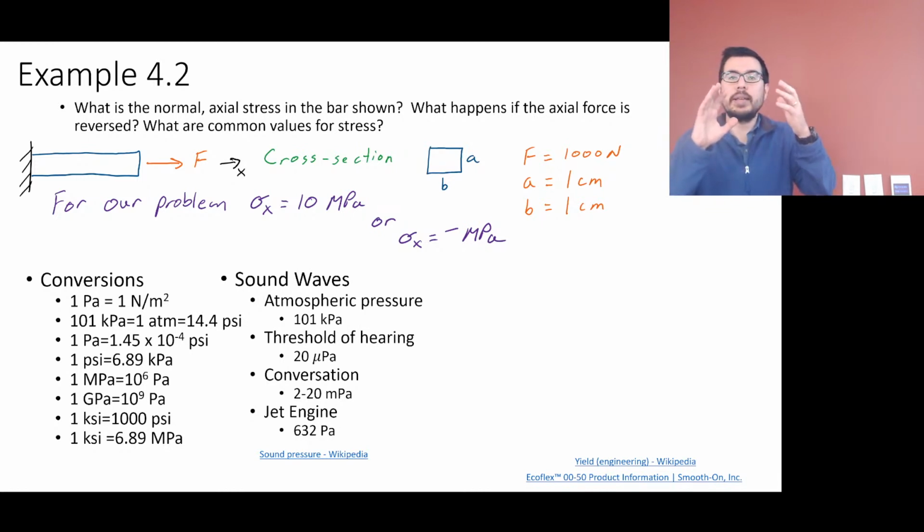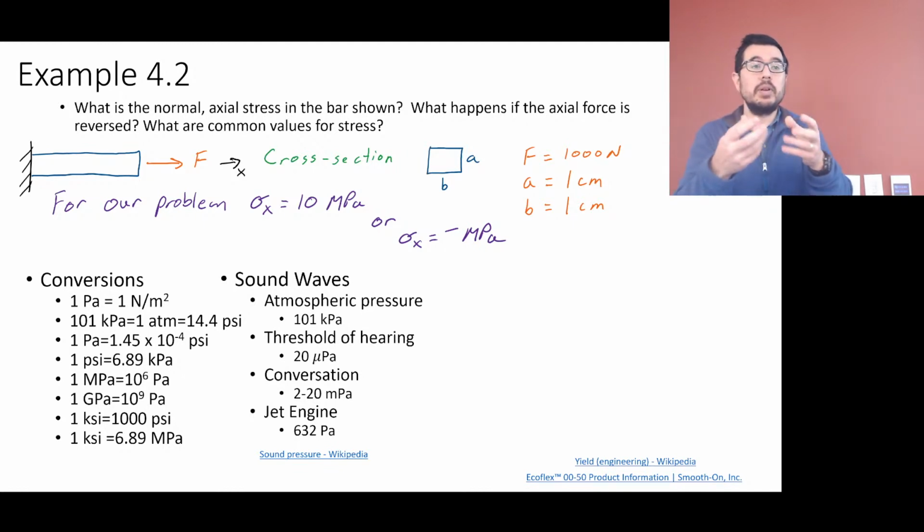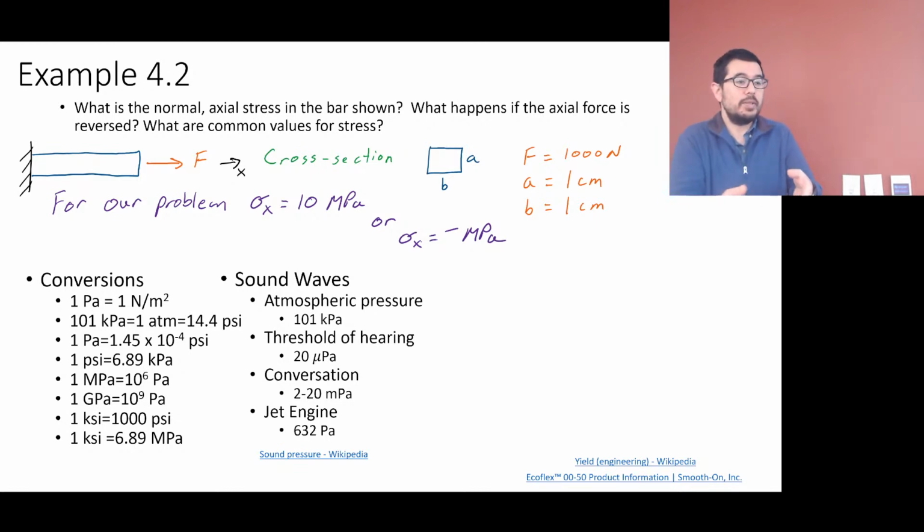When you put a cube into the ocean, remember rho g h is the pressure, h being how far, rho 1,000 kilograms per meter cubed, and g is gravity, 9.81 meters per second squared. As you have an object completely surrounded by a fluid medium, the stress is going to be the same normal stress on all 6 sides of that fictional cube.